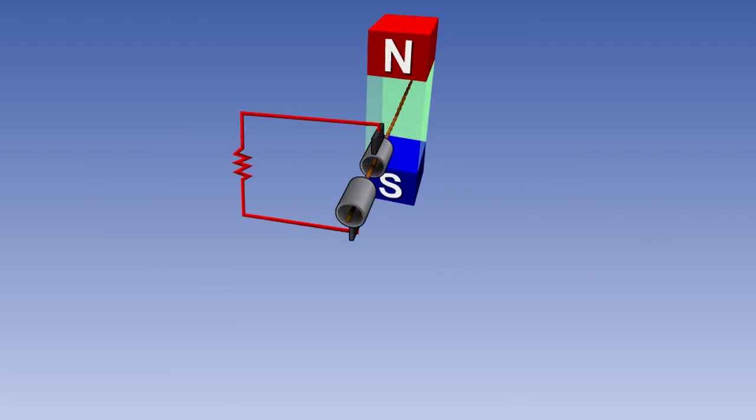The rotating armature AC generator is similar in construction to a DC generator in that the armature rotates in a stationary magnetic field. As it does so, an EMF is induced into it, and this EMF, rather than being converted to DC, as it is in the commutator of a DC machine, is taken from the rotating assembly as AC through slip rings.